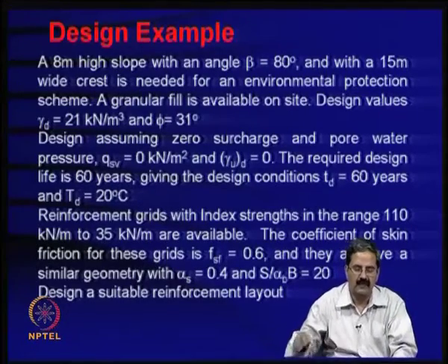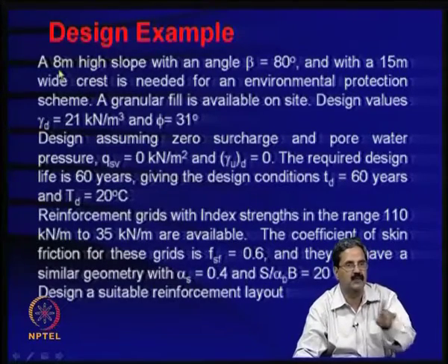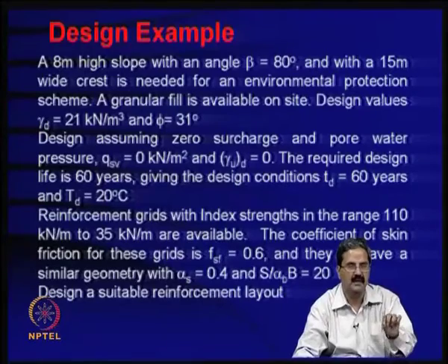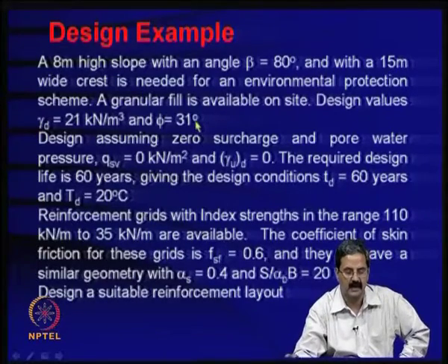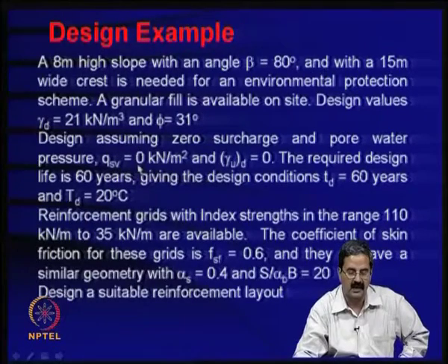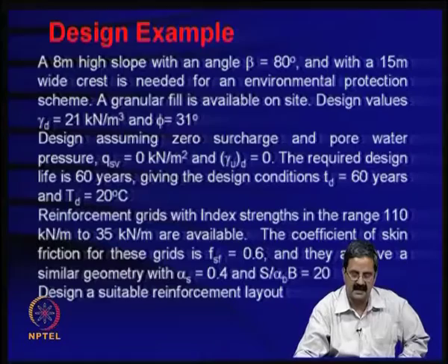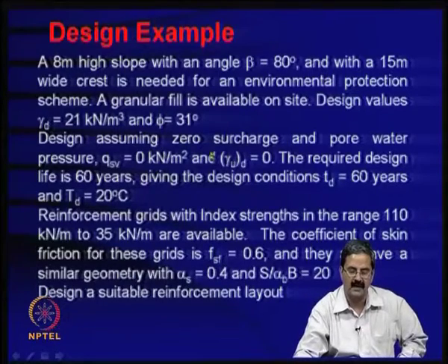So, when you have a surcharge, you assume that it is only 8 meter slope, but design it for 8 plus 1.1, okay. That surcharge effect is considered. In this case example I am only illustrating, but suppose you have a problem with surcharge, particularly when you are trying to design using IRC and other guidelines, you need to know how to handle surcharge, okay. The required design life is 60 years, okay.